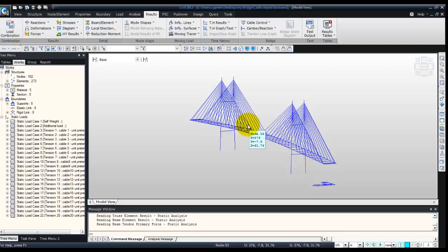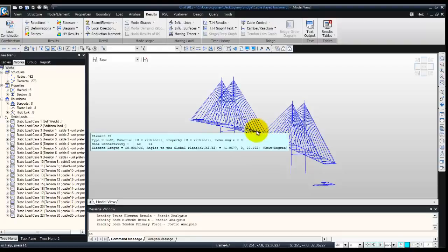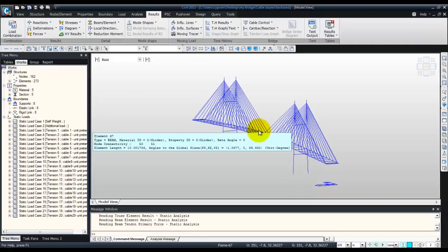Cable-stayed bridges are structures that require a high degree of technology for both design and construction, and hence demand sophisticated structural analysis and design techniques when compared with other types of conventional bridges. In addition to static analysis for dead and live loads, a dynamic analysis must also be performed to determine eigenvalues. Also, moving load, earthquake load, and wind load analysis are essentially required for designing a cable-stayed bridge.